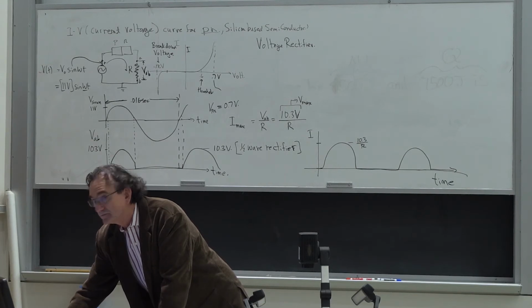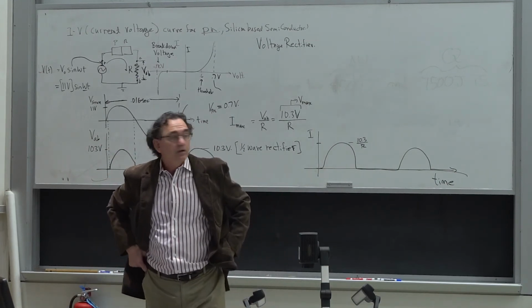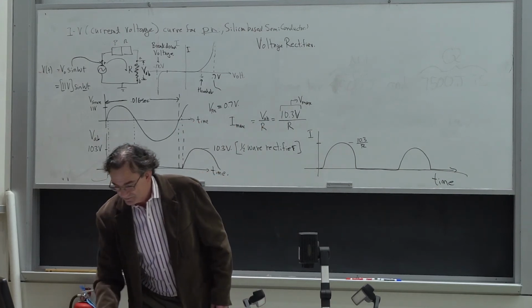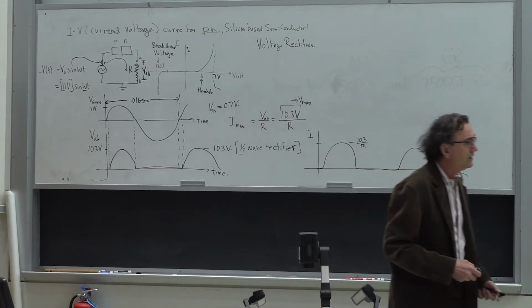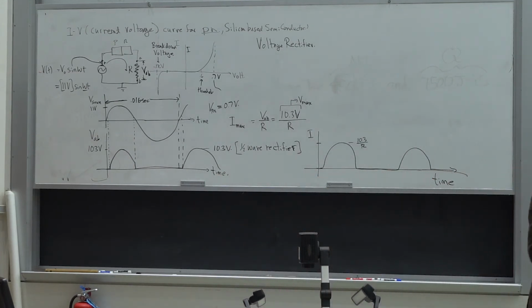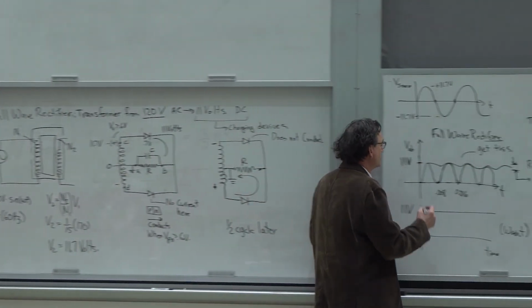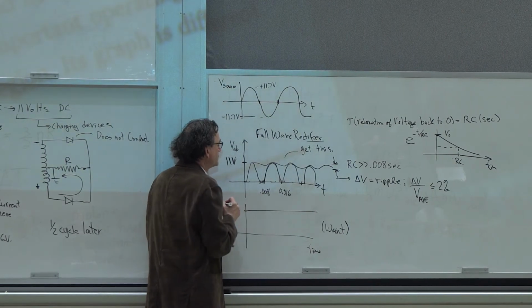Are we going to take the conduction angle into account? What do you mean, the conduction angle? Because the period is not fully 0.008, because of the fact that it gets to 0 before that. Yes, you're right. So there's what you might call an angle or a time period in here where it's 0.